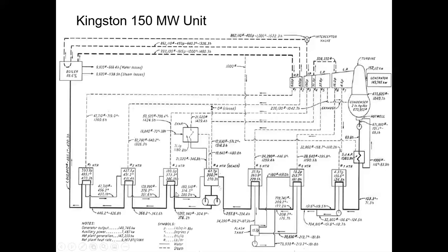Here's our main boiler feed pumps. This is the deaerator or the open feed water heater. We have to have one open feed water heater to help strip oxygen. These are all turbines. We go back to the boiler, as we'll see.